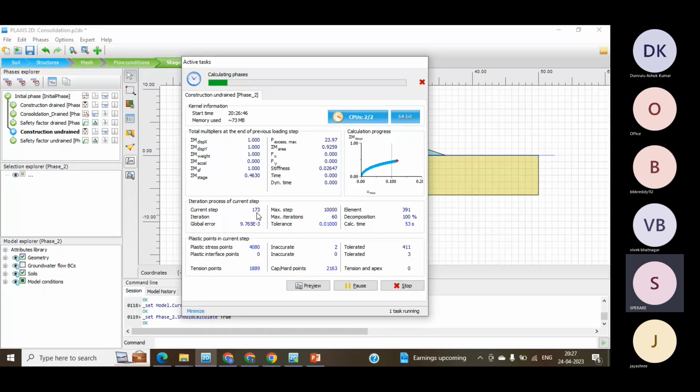So slowly it is increasing. This is where a Newton-Raphson method or a quasi-Newton method is trying to solve it. The small number of steps has been considered to solve this entire problem. It has reached the number of steps that you considered, but still it could not achieve the solution, is what it means. So to make sure that you achieve the solution, you increase the number of steps. That's where you can see the maximum number of steps value. Previously it was 100. Now I have increased it to a larger number. Sometimes it may not be satisfied with 1,000 steps also.